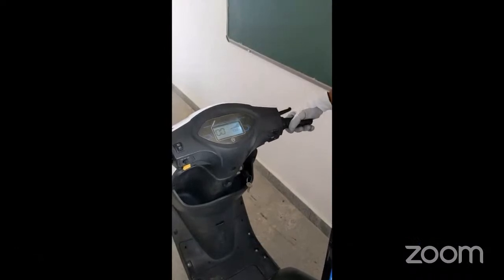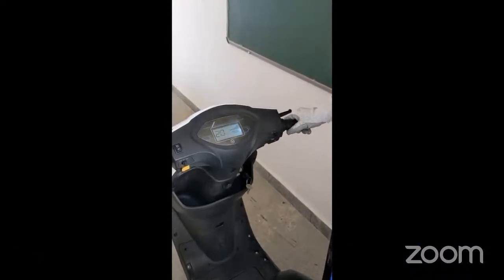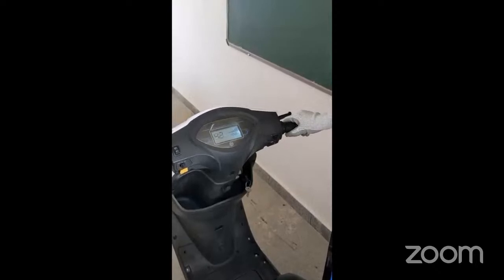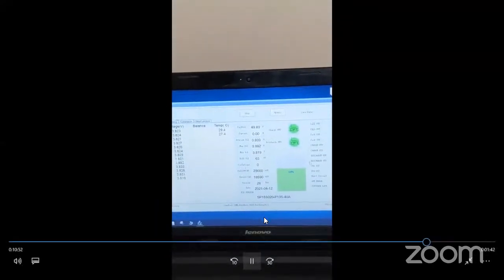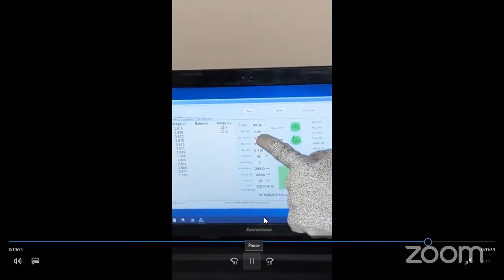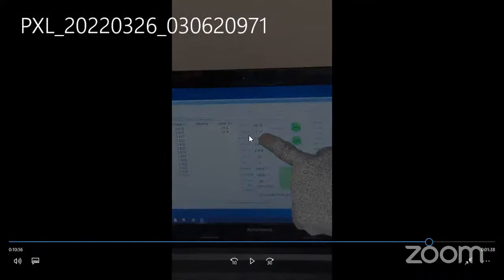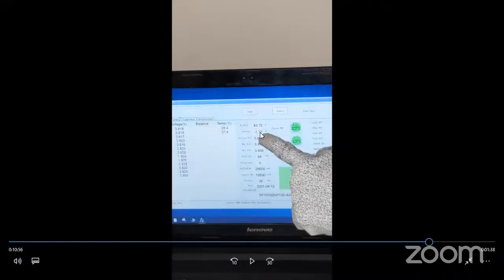Vehicle is on. I start giving acceleration. You can look at the window now. Current is 0. As soon as I give acceleration, it's showing minus 1.77 amps. Why the negative symbol? The negative symbol indicates that it's discharging. If there is no negative symbol, it says charging. If you are charging, it will be just a number with a positive sign, right? So 1.77, that's the value above the limit which you have set.